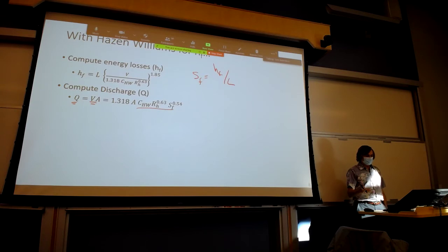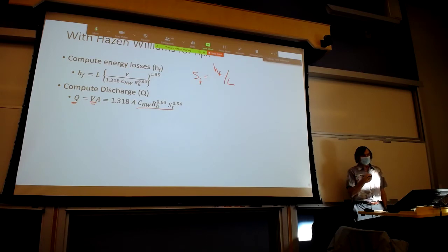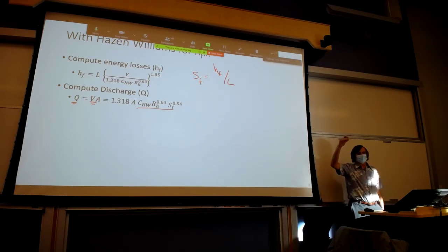The cross-sectional area is the cross-sectional area of the pipe, which you know in this class of problems. And again, in the discharge problem, what you typically have is a specification, for example, keep the pressure drop or the friction loss below a certain criteria. So that's how we did the problems when we were doing the Darcy-Weisbach form of this friction loss problem.